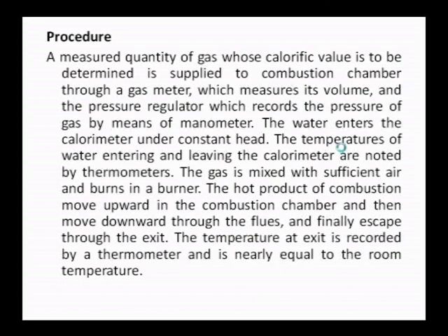The temperatures of the water entering and leaving the calorimeter are noted by thermometers. The gas is mixed with sufficient air and burns in a burner. For the combustion of fuel you require air. Sufficient air has to be drawn into the system, and we have to see that there is a complete combustion of the gas.